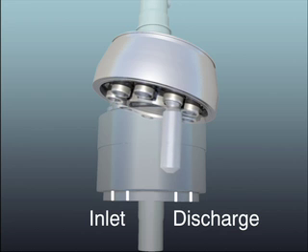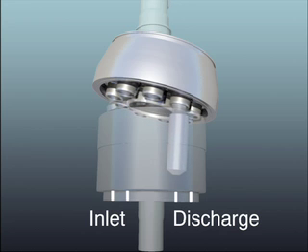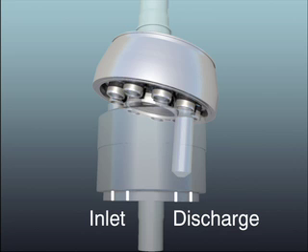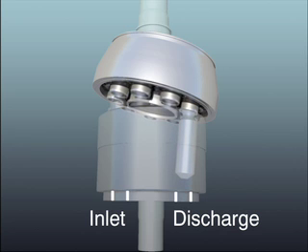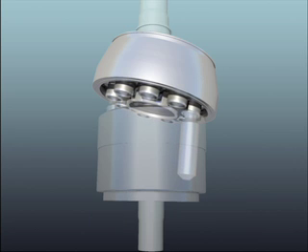As the piston moves toward the valve plate, fluid is pushed or displaced through the discharge port of the valve plate. When the piston is at the top of the reciprocation cycle, commonly referred to as top dead center or just TDC, the connection between the trapped fluid chamber and the pump's discharge port is closed. Shortly thereafter, that same chamber becomes open to the pump's inlet port.